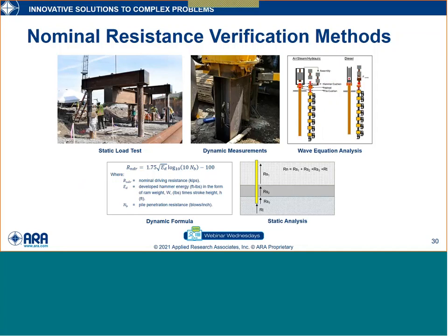Now, moving back to deep foundations as an example, but now to the construction phase. One of the great innovations that we've experienced in the last few decades is the means by which we can evaluate the geotechnical capacity. In this particular situation, I'm looking at a variety of tools that are available today and often used routinely: static load tests, dynamic measurements, wave equation computer analysis, dynamic formula, which may still be appropriate on smaller, simpler projects, and office static analysis. Now, we may have on some projects all 5 of these. Say, well, which one should we use?